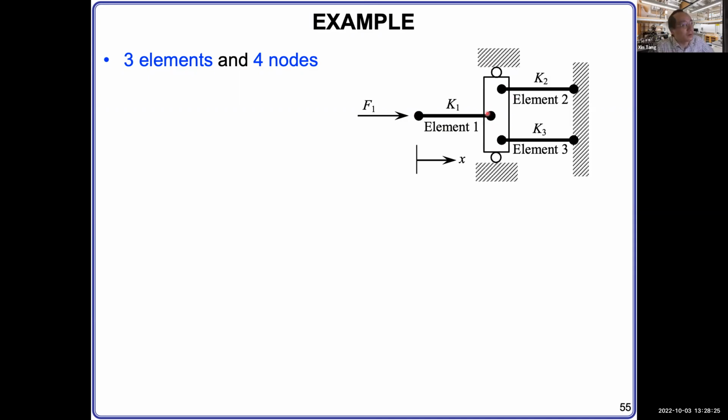It's only one node. And then the third node, and only one external force, if there is one. Okay. Here we don't have, because all the internal forces from the 3 elements cancel each other in equilibrium in this node. And the force from the top and bottom walls are zero. They are frictionless. Okay. So only 3 forces from 3 elements. Node number 3 is the element 2's other end that is bounded on the wall. Node number 4 is the same for the element number 3.